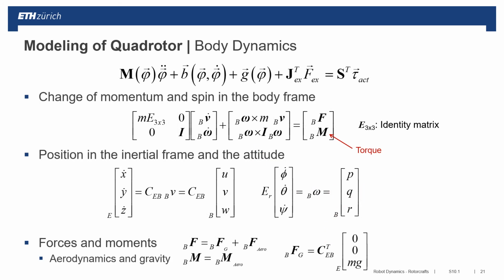So with the coordinate transformation and the rotational speed in body frame, we have all the elements which are required for the dynamic model of the quadcopter helicopter. So let us come back to the forces and torques which are acting on the system. In principle, we have the force and torque generated by the rotors, and additionally we have, of course, also the gravity force, which is very easy, looking directly downwards towards the Z direction in earth frame.